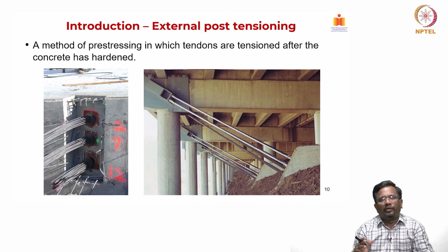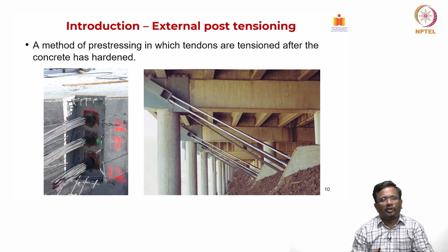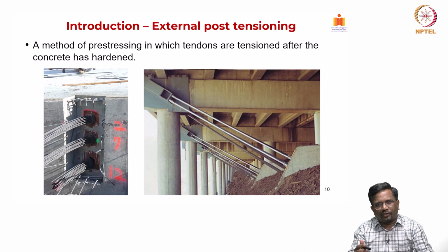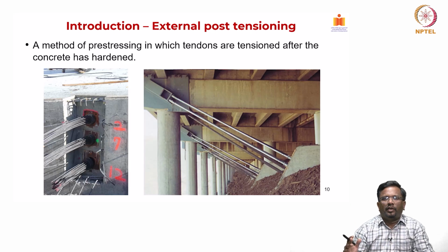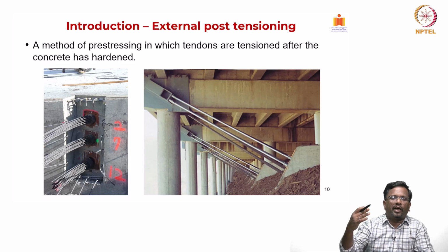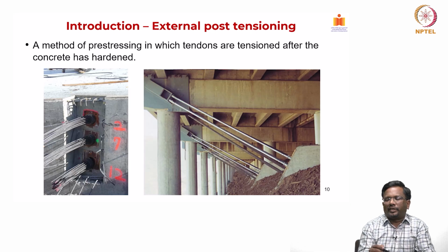As you know, we have talked about pre-tensioning and post-tensioning. In external PT, the PT elements are always outside the element, because here we are talking about structural strengthening. The structures have already been constructed, and after a certain period of use you have some problem, that means you can add an element only outside the existing structural element. So, that is the reason we call that an external PT.